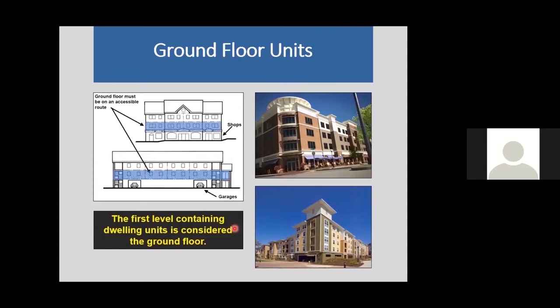If there is no elevator in the building, and again, this law does not require that you put in an elevator, we need to determine where the ground floor units are located in this building. They may not be at grade. This law requires that if you have a covered multifamily dwelling, you must provide an accessible entrance on an accessible route, unless it's impractical to do it by the site, not design choices, such as having perhaps commercial or retail at grade, or a garage space at grade.